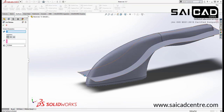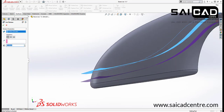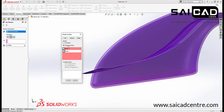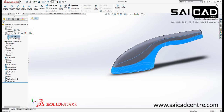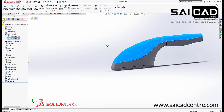In that we will have to select the face. Now you can see there is a thickness, and I will make that value 0.1, and create that on both sides. Click OK, and it asks whether you want to keep some selected bodies or all bodies. I want to keep all bodies. Click OK, and here are the bodies. If you go here, under solid body, we have cut section 1 and cut 2. So like that you can create your objects.